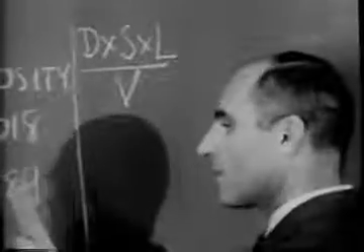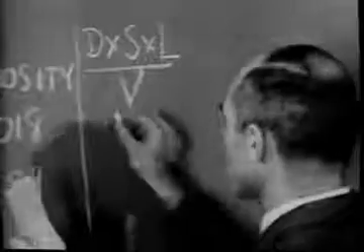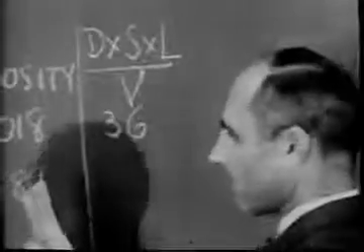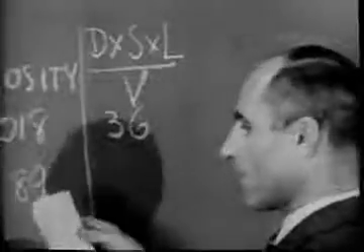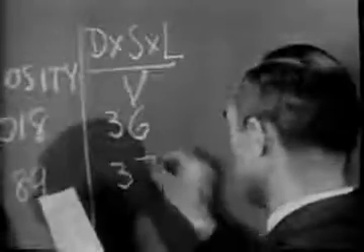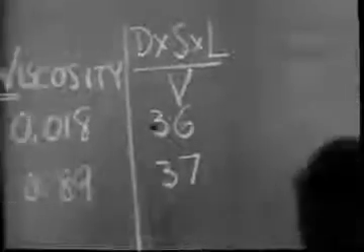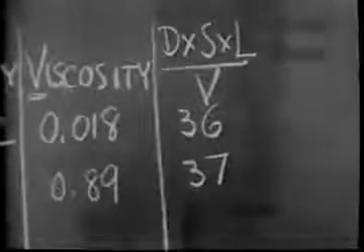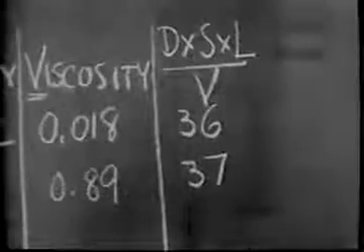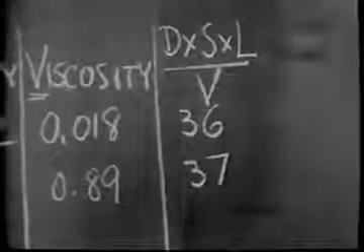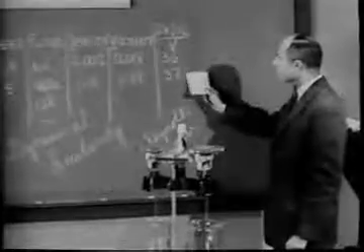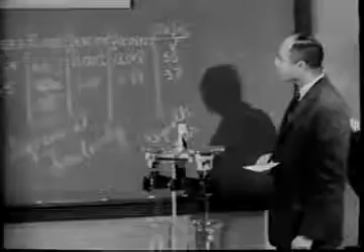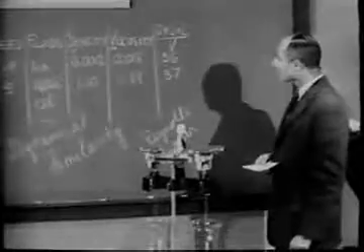You can see that for the experiments we selected, the Reynolds numbers differed by only a few percent. So while these two experiments, one in a gas, one in a liquid, appear very different to the eye, they are dynamically similar. And as you will see later, from a measurement of the drag of the plastic ball in water, this similarity enables us to predict the drag of the helium balloon in air.